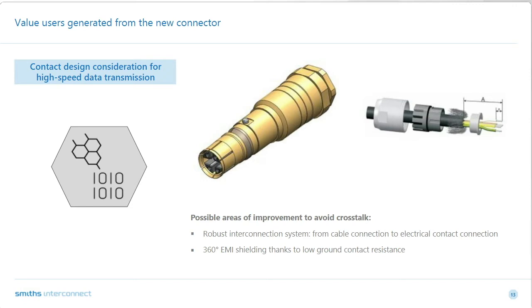Now, for example, in electromagnetic compatibility of an auxiliary power electronic system of a use case that we came across in London Underground, there can be multiple ways that EMI can be generated. For example, in signaling interface, in magnetic fields, for example, coming out of telephone interfaces, or radiated radio frequency emissions, or your radio frequency interface immunity. Now, good EMC connection is achieved with the shielding connection over 360 degrees with low ground contact resistance.